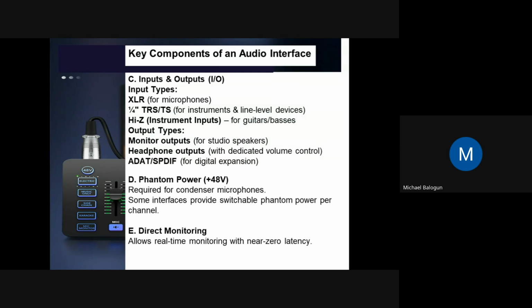Most times a standard mixer has a phantom power which you will engage, because if you plug your condenser mic in and don't phantom power it, it will not work. Some audio interfaces have phantom power, like this one.